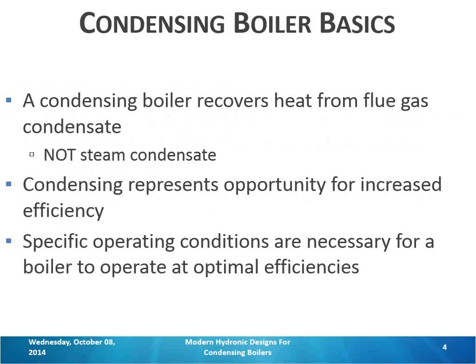But to get there, we need to cool down the water coming back to that boiler, the return water. You get that steel or whatever material that boiler is made of cold enough, and just like a cold soda can outside on a humid summer day, you get a layer of moisture forming on the surfaces. And then that heats up the steel, which then in turn heats up the water, and you use it to heat your building. So the phase change has to happen inside the heat exchanger itself. If it happens somewhere else, say in the stack or outside, you're not actually making that available to your system.